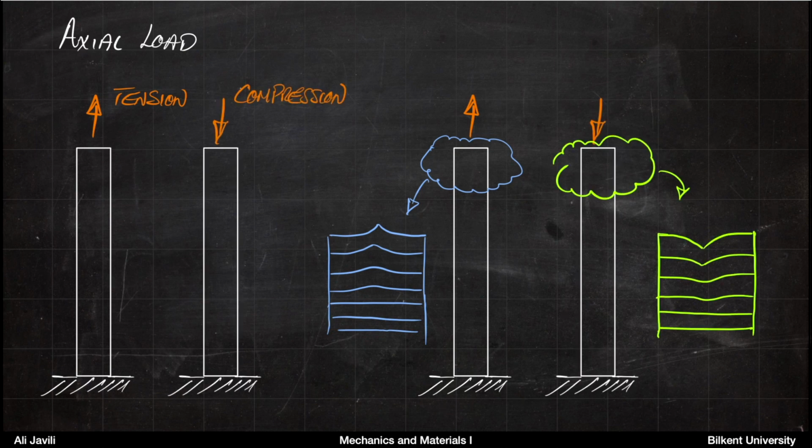The same thing holds for a compression test. So again, if you now compress the same bar, instead of applying a tension load, you apply a compressive load downwards. And if you look at the region close to the point at which you apply the force, you can see a very clear influence of the force exactly where the force is applied. But when you come down, and if you are sufficiently far, then you do not know exactly where the force is applied. So you only see the influence of the force as an average effect. You don't see that strong local effect.